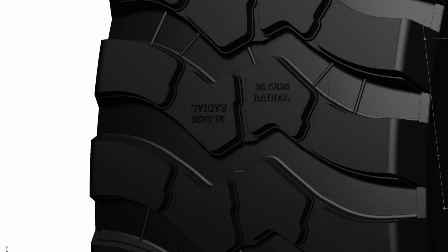You get used to having a lot of sketches in the way. Sometimes it looks like a mess of things. Often when you're doing CAD design, because you're the one working on the model, you understand where all these sketches are that are driving different features, and it doesn't get in the way. You actually want those sketches in place while you're working on the model. To other people, it may be overwhelming. So making sure that the model is structured in a way that you can turn those things off or hide them, and then the person can roll back, uncover things and discover how you've built the model. That's pretty important to CAD modeling in general.